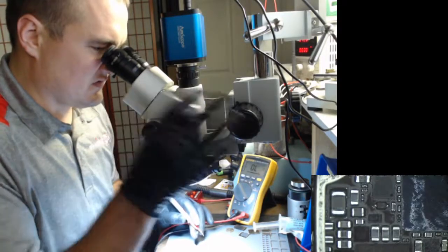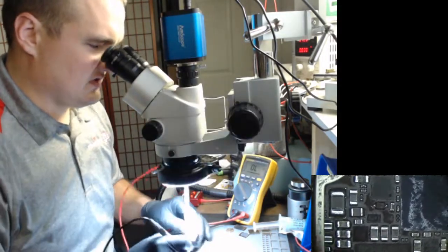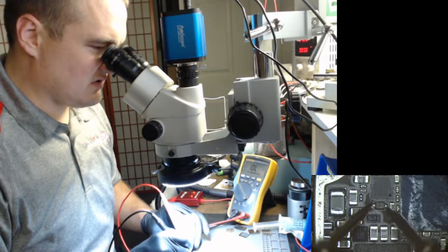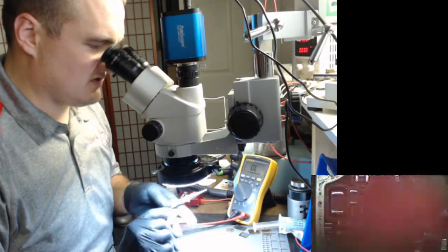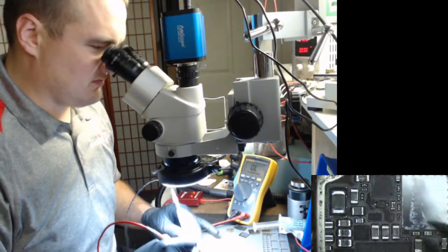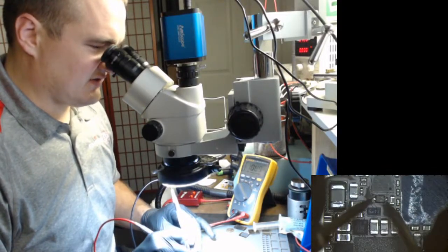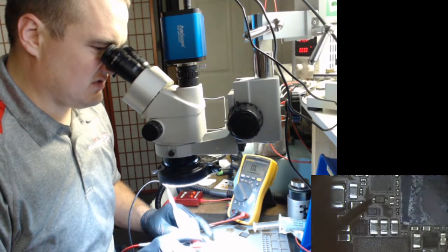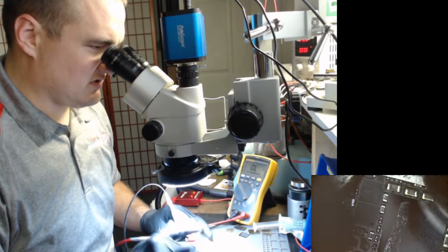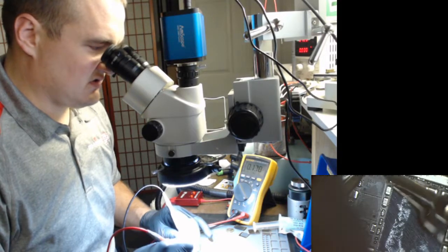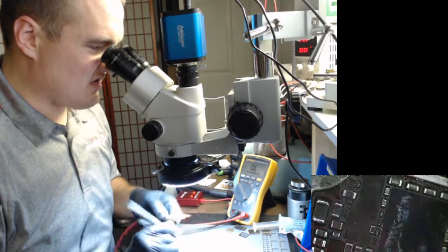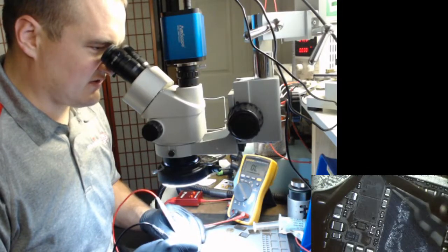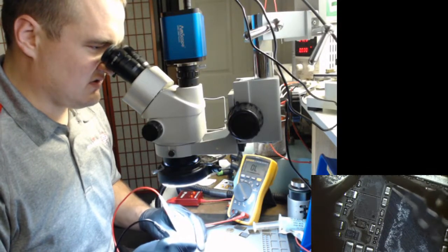Okay. So red, black. Oh well. Swap them around. Black, and then we're going to send to it. We got 0.179. Okay. 0.178. I think we already know the answer. The backlight circuit's fine. It's bueno.